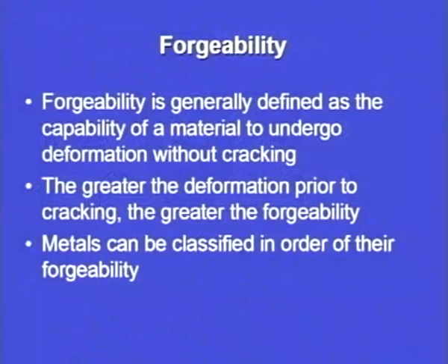So, the greater the deformation prior to cracking, the greater the forgeability. Whatever deformation we can get before the limiting factor of cracking is achieved, we say that this material is forgeable up to that limit, or can be plastically deformed up to this limit, after which the cracking will start.